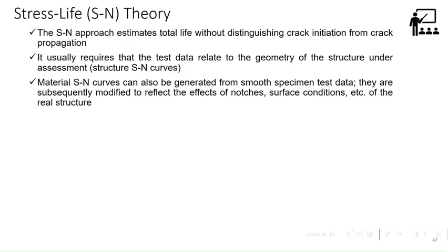A material SN curve may also be generated from smooth specimen test data. They are subsequently modified to reflect the effects of notches, surface condition, etc.